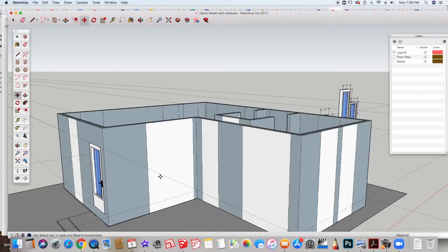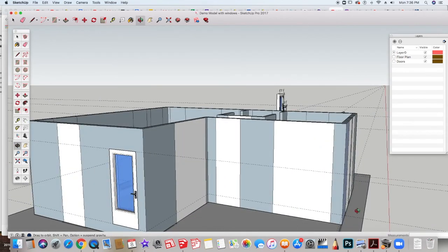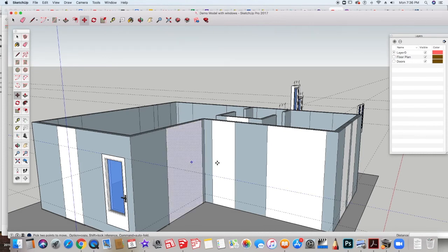I put the door in, and you might have seen already that I made a slider that's going to go in here and here, and there's another window that's going to go in this top part, and it's only 1.5 feet. So I need to establish where the heights of my windows are going to be. And I have one window that's 8 feet tall. So I think I'm going to start my lines for all the heights of my windows at 8 feet so that they all go from that 8-foot mark down.